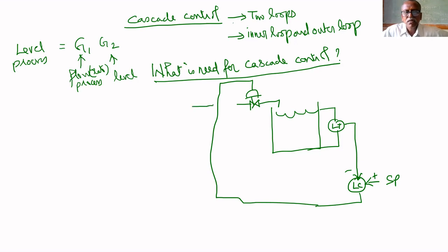Here, the flow rate is a function of valve opening M, upstream pressure, we can say it is PI or UI, as well as downstream pressure. But downstream pressure is, in this case, open to atmosphere, that's why it is constant. But upstream pressure may change.